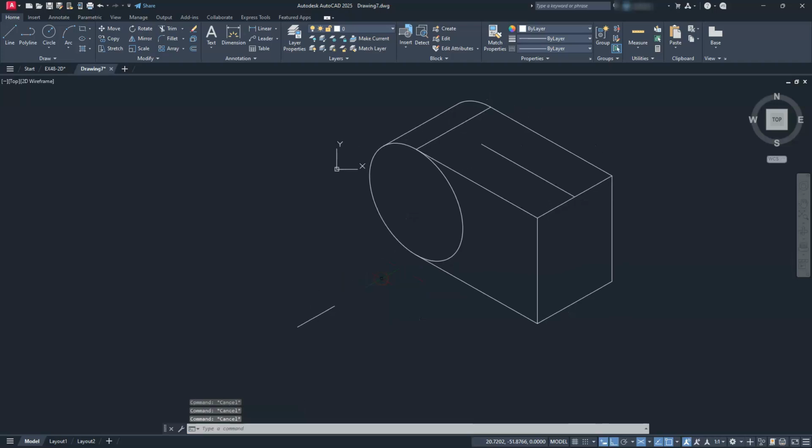Let's go ahead and move that. So just go ahead and move this line from this midpoint to that endpoint. Okay. So now we know that this line will come right to where it hits this line. So I'm just going to go ahead and copy this from this endpoint going to that endpoint and this one.